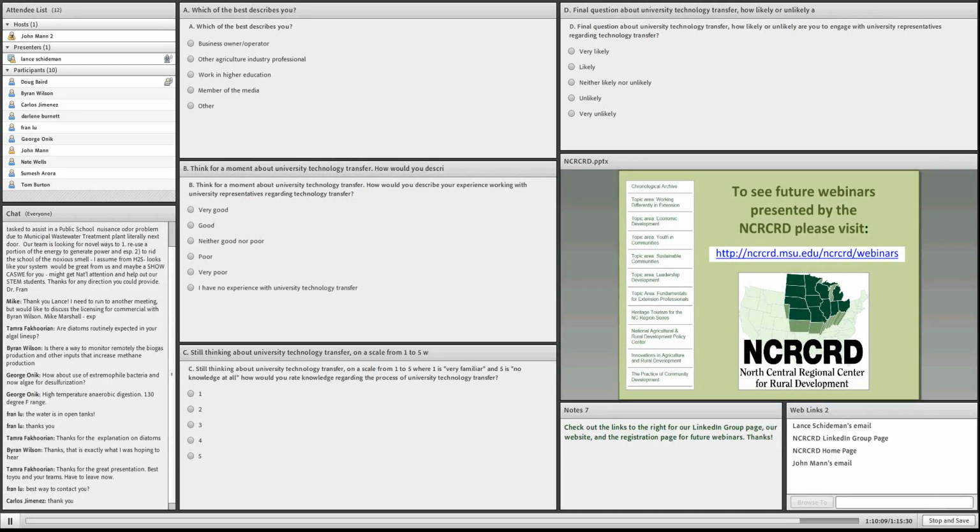So I see the question about water in the open tanks, and yes, conventional wastewater treatment is typically done in open tanks. There is some latitude above which you will need covering on the tanks. Conventional wastewater treatment plants throughout the U.S. don't generally have to have covered tanks because the wastewater has enough heat to keep them from freezing.